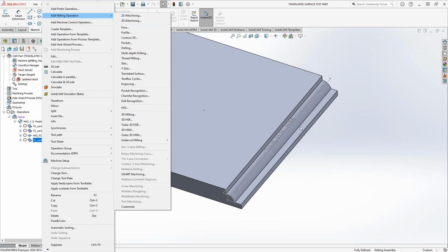And the drawback of this one also is that it needs a path and a cross section. So if that cross section is inconsistent, or you've got multiple paths to follow, either generate a whole bunch of toolpaths or use some sort of recognition toolpath where it does all of it. So this is a very limited toolpath, but yes, you could do very similar things if you had a solid and you had 3D milling.